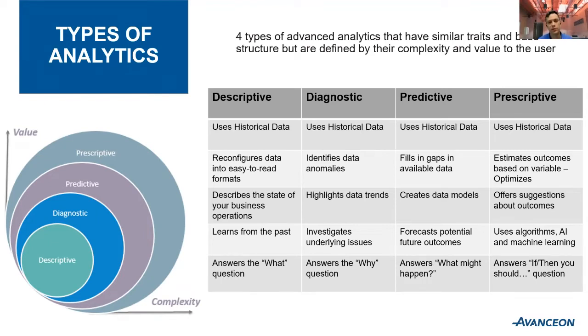So in this case, we looked at 10 CIP circuits that each had two loops, one for temperature and one for flow. And we reviewed over 2 years of data in order to help identify patterns and trends and to develop some insight into the reason for those losses, along with some potential resolutions to address them. For this particular project, we pulled together a report card of their current performance and then provided a detailed recommendation and action plan to help close those gaps. Currently we have a subsequent project going on that's addressing these different root concerns.